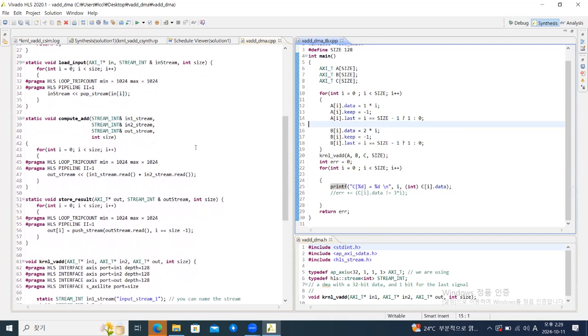If you use the HLS stream, you should probably have an architecture. DMA is a black box from the IP's perspective. But what the DMA does is that you basically have a FIFO, which is the in stream, and the DMA will fill data.